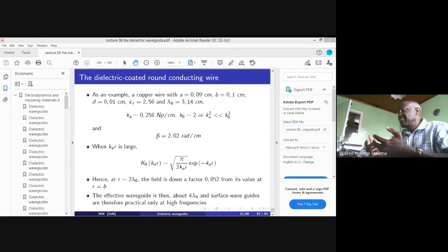So please be careful when you're working with this, and remember when you're dealing with transmission lines that sometimes when you are looking for line lengths, the line lengths must be positive, and sometimes you may get a value that is negative. That is an angle or an electrical length that is negative.